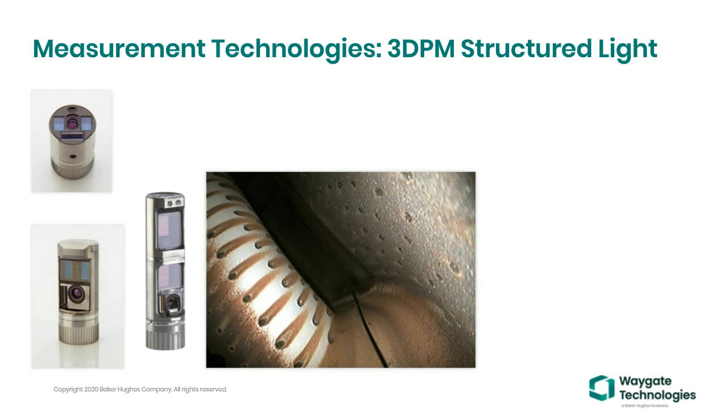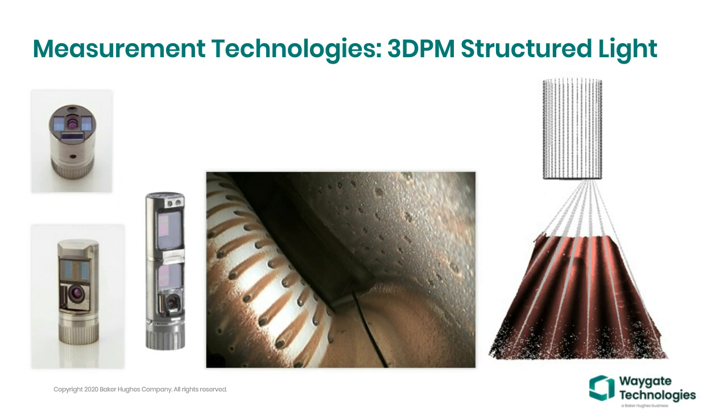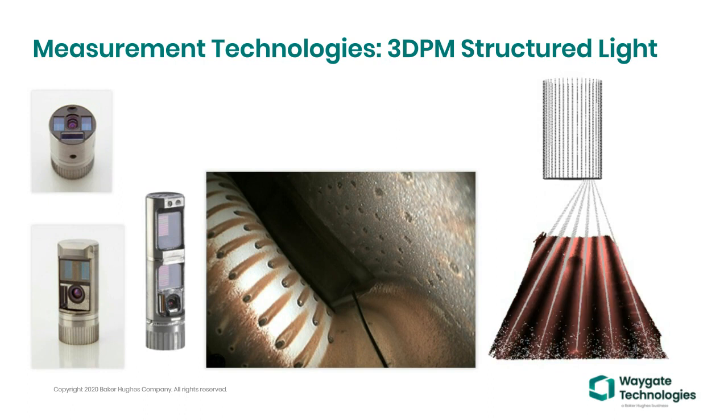And recently we've released a far focusing and farther measuring side view tip. That's the long one in the middle of the image there, and you can see the fringe patterns at the top and bottom, those fringe pattern generators that are above the optical imager. Now, you won't see this when you're capturing an image, but what happens is those fringe pattern generators fire sequentially and generate a series of shadows or fringe patterns onto the targets. And what is going to happen is that a series of these fringe patterns are collected and compiled to form an XYZ point cloud.